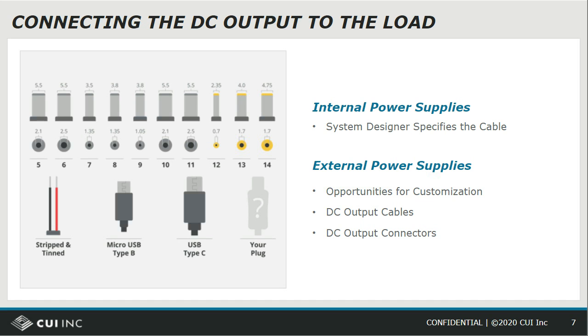And typically in power, you may see 4 contacts in the DIN connector, and they tend to be slightly higher current. They're physically bigger than a barrel connector or a USB connector. In addition to the electrical connection, you may choose to have latching on your DC plug so that the DC plug cannot inadvertently be disconnected from the jack into which it's plugged.